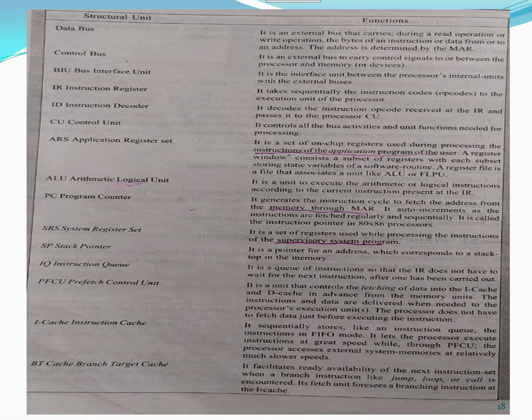Stack pointer, where we are using this particular pointer for the pointing of the stack where that particular data is being stored inside the stack. So stack is mainly used in the interrupt processing. So whenever an interrupt occurs, at the time of interrupt, the status of all the registers which are important for a particular microprocessor's operation will be stored in the stack.